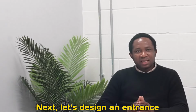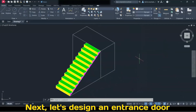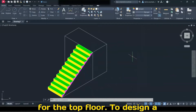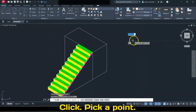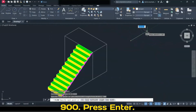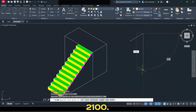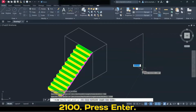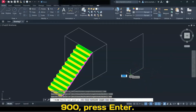Next, let's design an entrance door for the top floor. To design a door, click the polyline tool. Click, pick a point, track 30 degrees, type 900, press enter. Track down 270 degrees, type 2100, press enter. Track 210, 900, press enter.